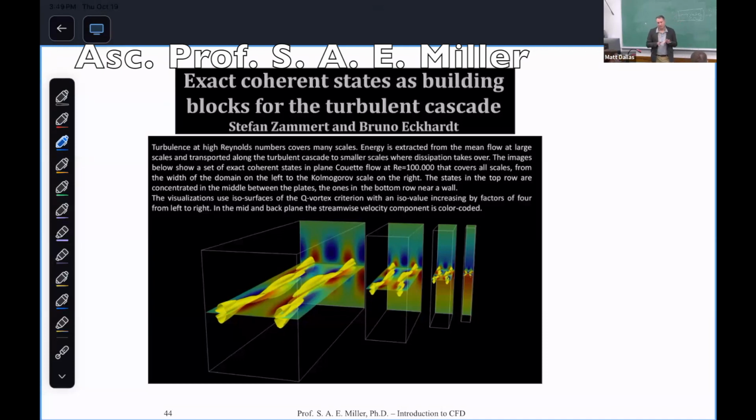in the Navier-Stokes equations, say I have U, that's the velocity. For every variable, you just say U equals U bar plus U prime. U bar is a time average variable, and the prime is the fluctuating variable. You can take any variable and decompose it into its average and a fluctuation value. That's called Reynolds averaging in the business. And I take that averaging quantity and put it in the Navier-Stokes equations.